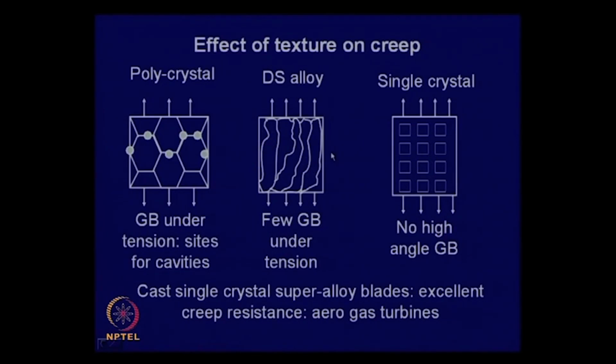that does not have any grain boundary, but again we need to have precipitate. In nickel based superalloy, you have gamma prime, and these gamma prime precipitates are coherent precipitates. Coherent precipitates have low surface energy, they are highly stable, and their growth rate is minimal. Therefore, they have high structural stability and you have a large volume fraction of precipitate, while the overall structure is a single crystal, with no high angle grain boundary. So, they exhibit very good creep resistance.